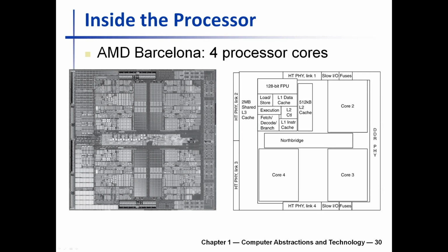Then here you have a load store unit, which lets the CPU put things in the memory and bring things from the memory, right? So the logic that handles those operations is here. And here you can find the rest of the execution other than floating point. The integer execution can be done in a smaller logic circuit here. Then this part of the CPU is about fetching and decoding instructions.